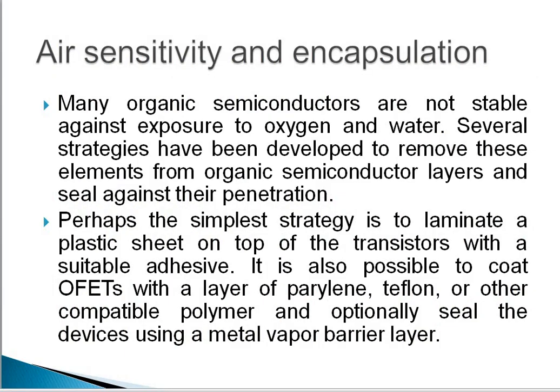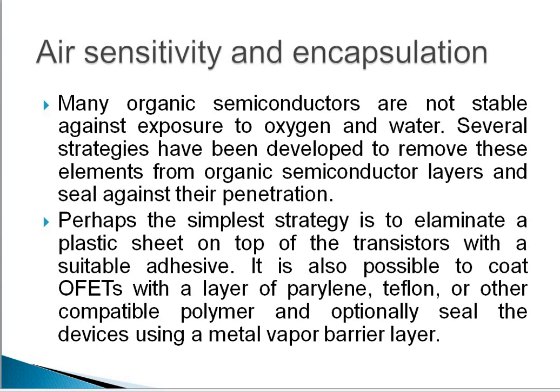Next is the air sensitivity and encapsulation. Many organic semiconductors are not stable against exposure to oxygen and water. Several strategies have been developed to remove these elements from organic semiconductor layers and seal against their penetration. Perhaps the simplest strategy is to laminate a plastic sheet on the top of the transistor with a suitable adhesive.